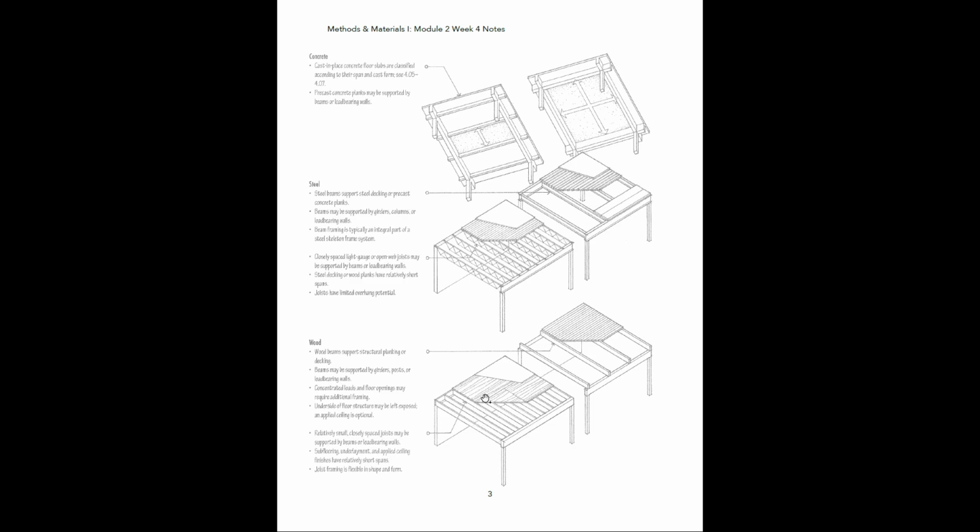Our subfloor, like I said, is going to be screwed down or nailed down to this joist. And then it will also usually have an adhesive applied to it that is going to also keep it tied down tight to the joist. And we're going to talk about that in a little bit too. But then on top of that, we're going to have maybe an additional layer, or we will have our finished floor layer. All right.